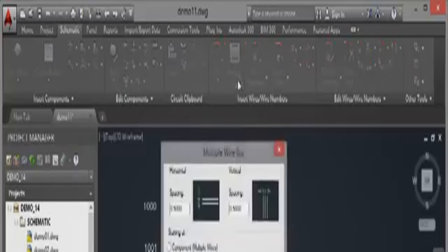If I go here to multiple bus, again on the Insert Wires Wire Numbers panel, I've got horizontal spacing, vertical spacing, 1/2 inch each way. I've got component, multiple wires, another bus, multiple wires, empty space horizontal, empty space vertical. If I go another bus, multiple wires, and make sure that the phasing is the same, so it's 3 there,